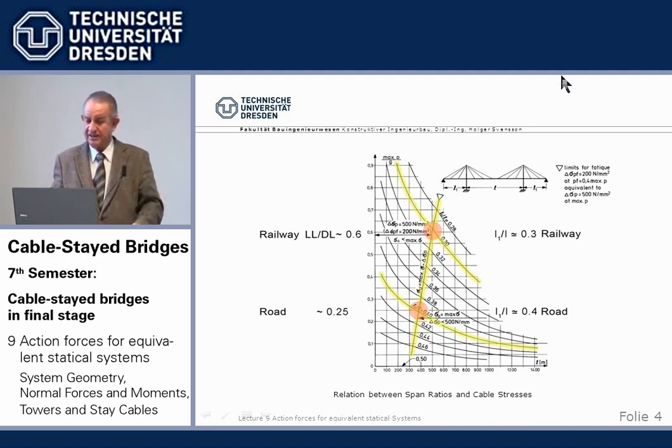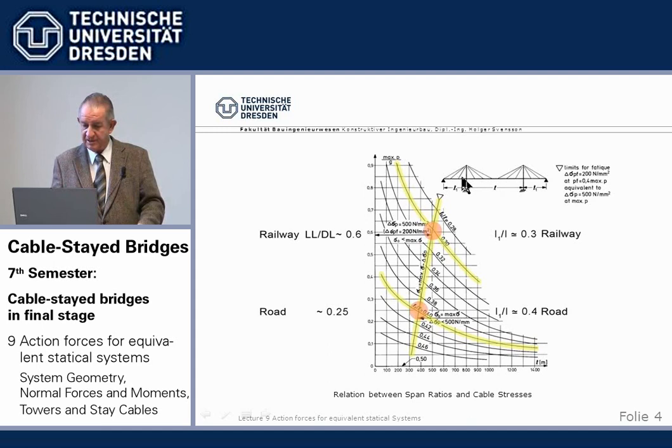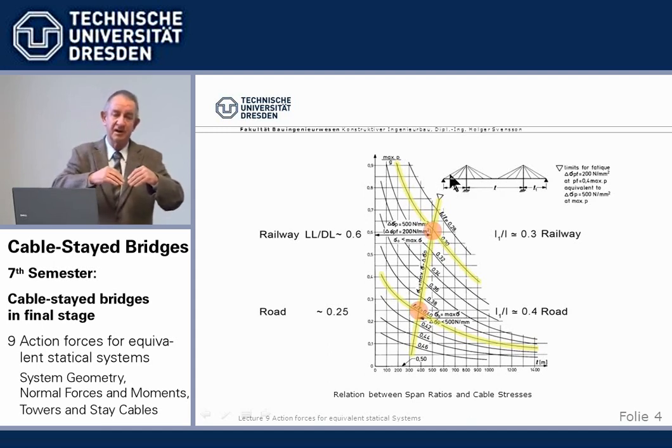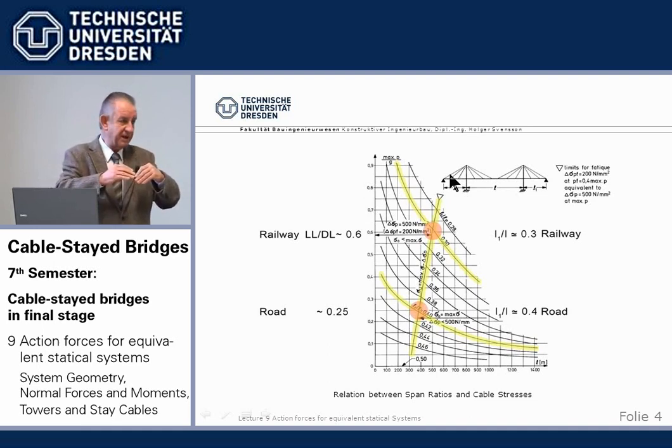On one hand, these live loads in the main span stress the backstay cable. The more force, the bigger the cable becomes. The bigger, well, the more costly, so we want to keep it to a minimum. On the other hand, if we have in addition the side span, we get compression in there from live load. So we have a fatigue loading in the backstay cables.